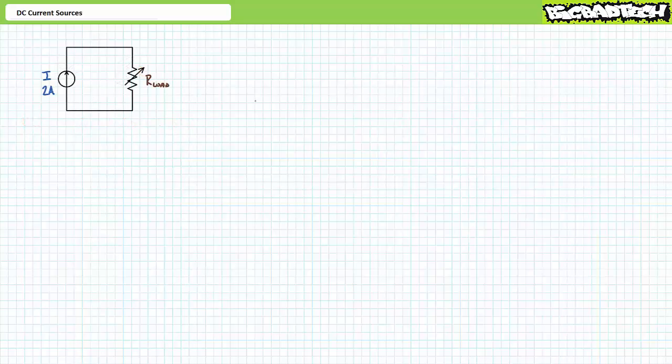This is the schematic symbol for a current source. It is a two-terminal device and induces conventional current through a circuit in the direction indicated by the arrow. This is a mathematically perfect entity and not necessarily constrained by reality. In theory, a 2 amp current source should push 2 amps through a 20 ohm resistor just as easily as it would push 2 amps through a 20 mega ohm resistor.